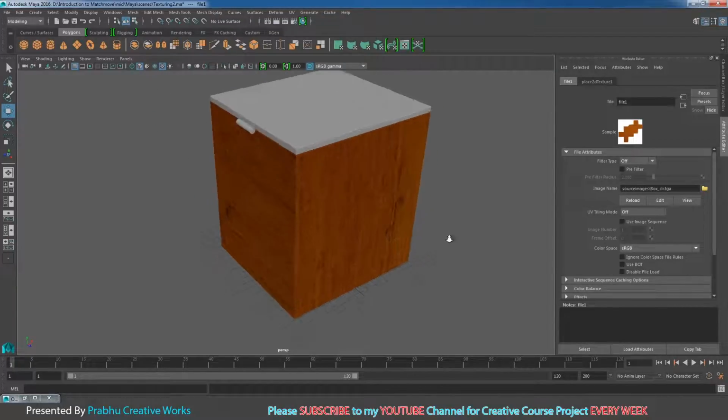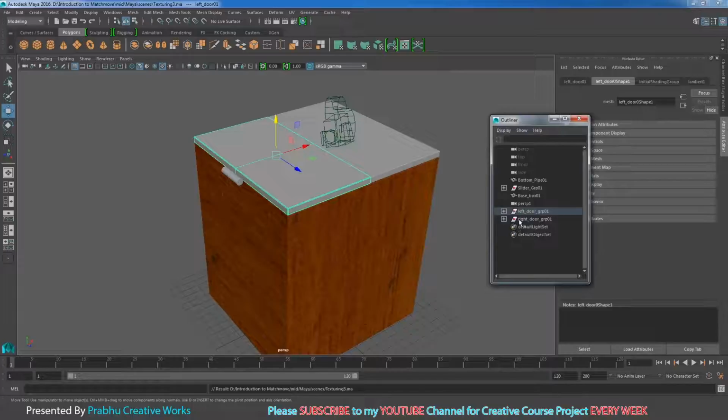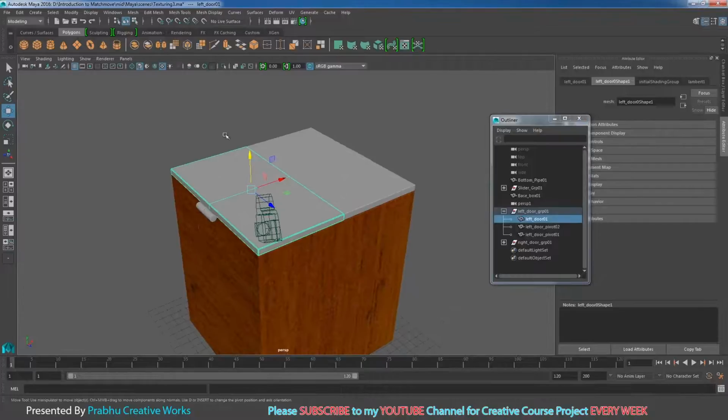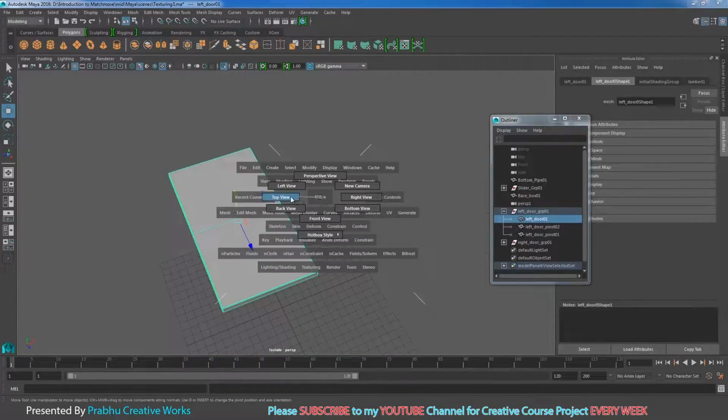So okay, so now I want to make texture for this box. Okay, open outliner. So and go inside of our left door group 01. So and then you want to select the left door 01. So inside. So now I isolate select this object over here. So now go to top view.